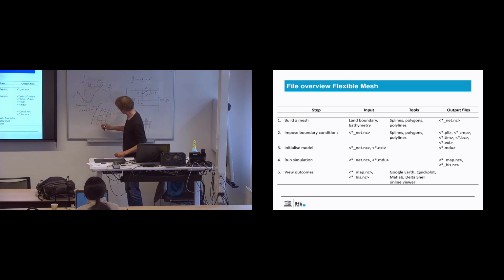And at initialization, the model will shoot out virtual links on the upside, and it finds the crossing points with the polygon. And those crossing points actually determine the positions that mark these cells as being boundary cells. And that generates these stars from my previous slide, these blue stars, if you remember, the boundary ghost node stars. It generates these positions, and at these positions, we will apply the boundary